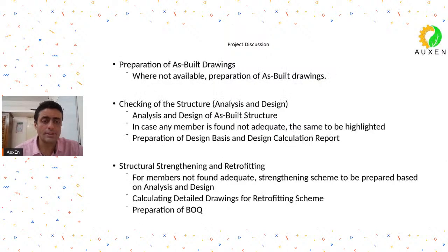Then comes the preparation of as-built drawings. So suppose you have got some drawings but they are not up to date. What you see on site actually is different from the as-built drawings. Let us say because over the period of time there were modifications, changes, whatever. So if as-built drawings are not available, you prepare as-built drawings. That will be the third step.